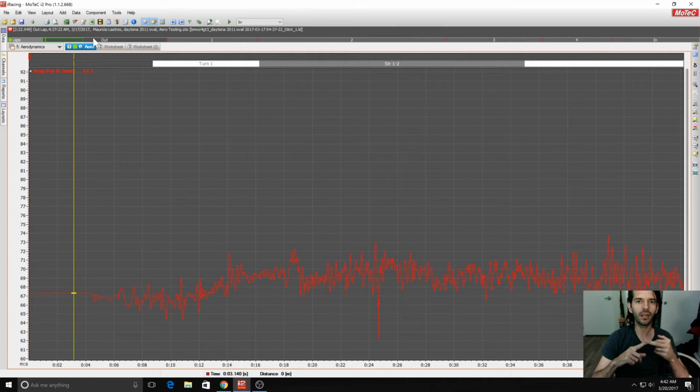And then after that, I'll speed up again, bring it down to 150, just so I have a really easy way to tell on the telemetry where I'm at. And then I'll do a coast down test where I'll push in the clutch and just coast down to almost 0 miles per hour. And then from the coast down test, we'll get our coefficient of drag and our rolling friction.